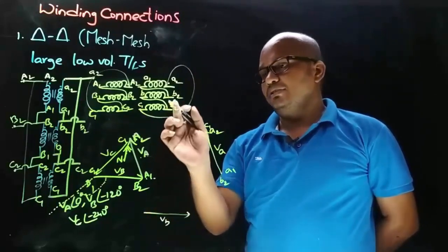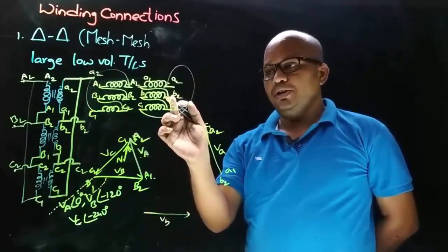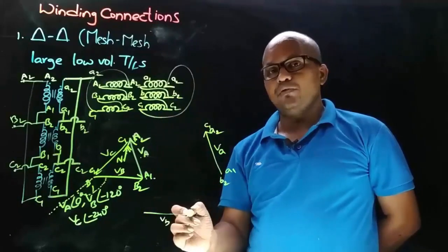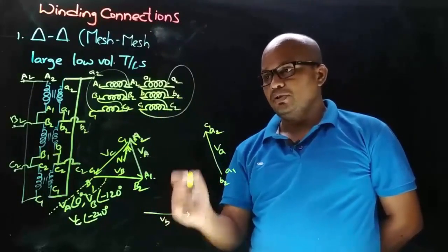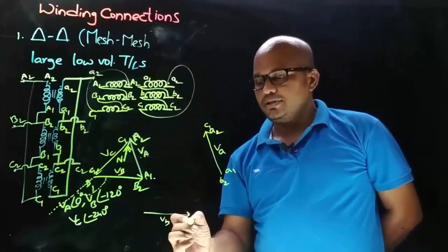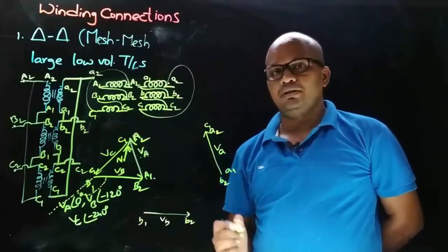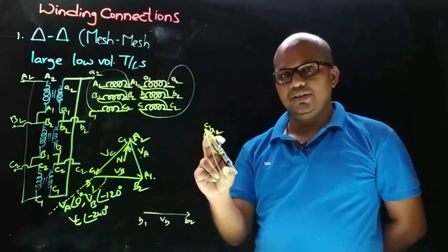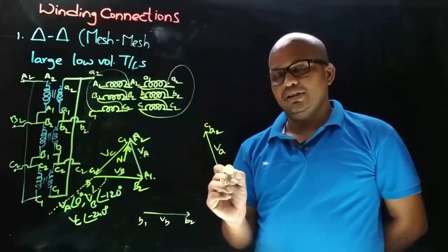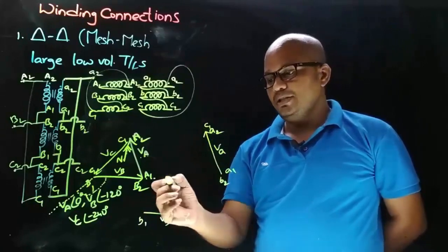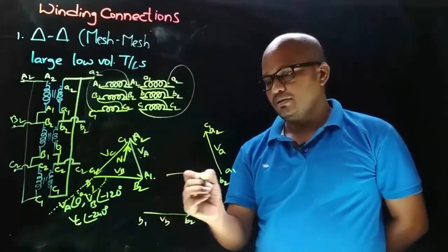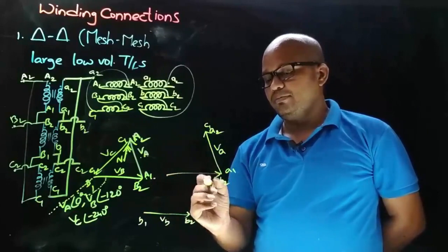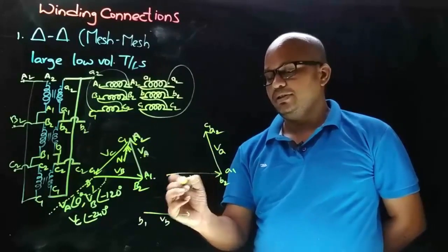As here the connection is taken on dot end and arrow always points towards the connection we took from, this is B2 and this is B1. And now we need to connect this secondary side VB phasor with secondary side VA phasor. As this A1 terminal is having B2, the VB phasor will be here like this.